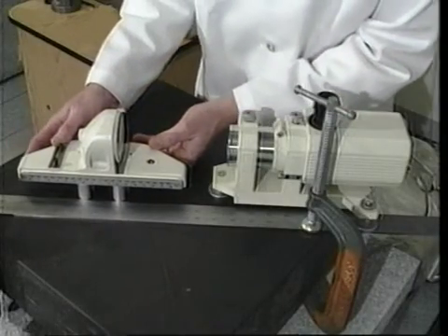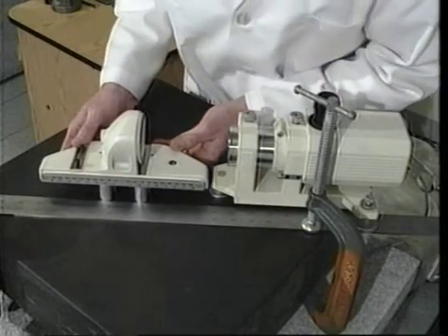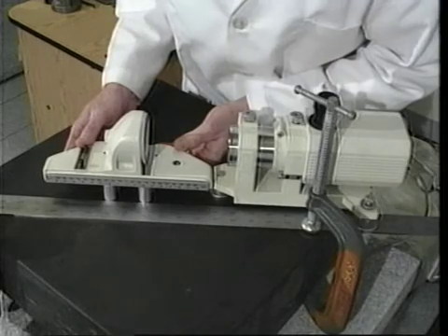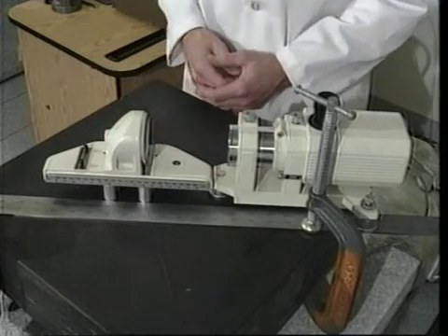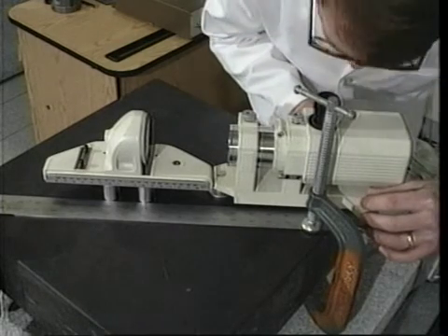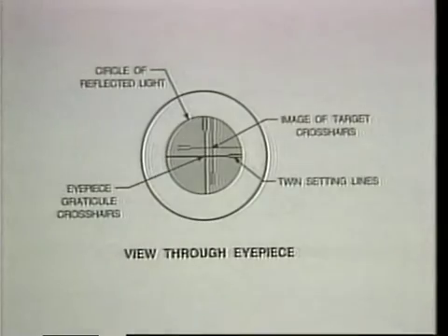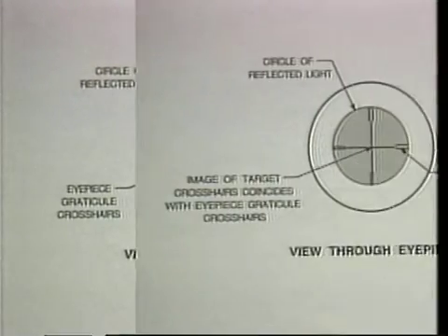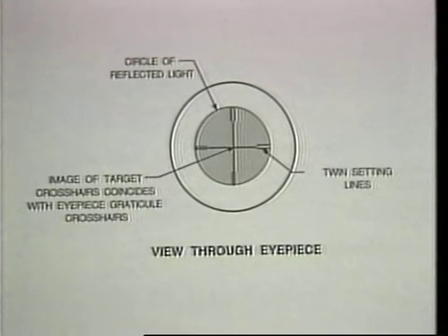Carefully position the reflector at the closest measurement position, making sure that the feet are positioned against the straight edge. Align the optical unit with the measurement path. Adjust the position of the optical unit until the image of the crosshairs comes into view. Continue to adjust the position of the optical unit until the graticule crosshairs and the returning image are aligned.